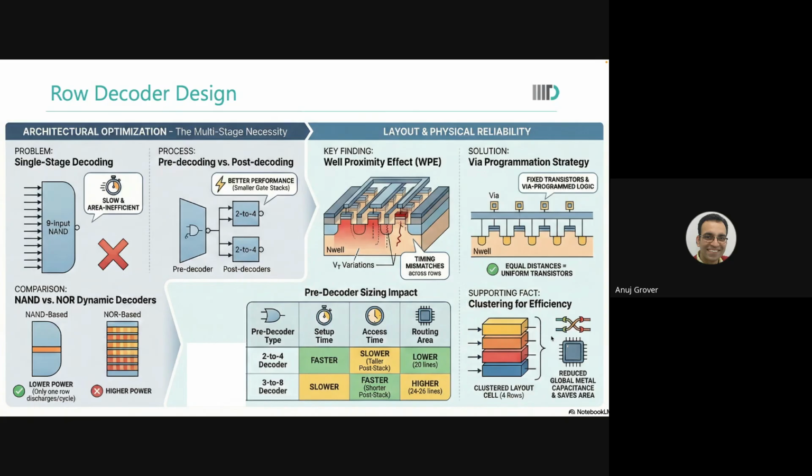Exactly. In ROM also, the programmation is done exactly like this, that you tell where, which. So now here you have to have a logic in the sense that where will you put all those VR1 labels? You will put drop VR labels beneath all the metal 2 lines that you're using for programming, which are outputs of your, let us say, 2 to 4 decoder in the pre-decode region. So beneath that, wherever you have the intersection, you will put those labels. Now, which label is to be used for dropping the VR is a part of your logic.